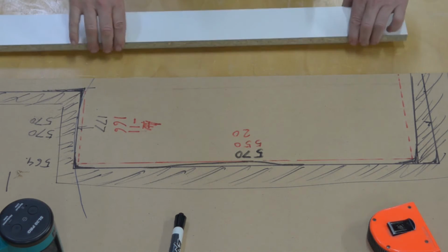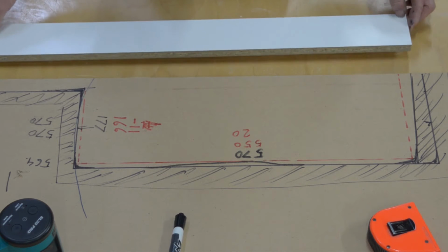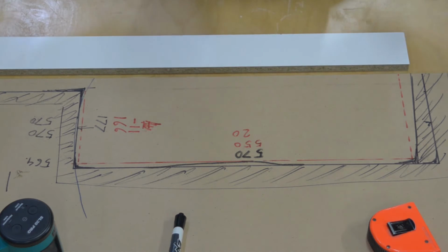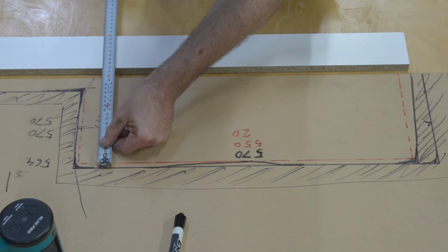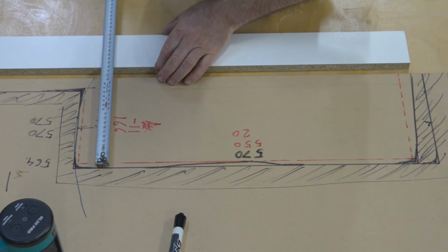So you can use that to examine a plank or a piece of aluminium or whatever's kicking around the building site to find something straight that's long enough. And then you can lay that down somewhere. They're usually going to weigh something, and you can measure. Okay, this is our wall. This particular dimension here to my plank is, say, 200, and I'll make it 220, so I've got a consistent space.